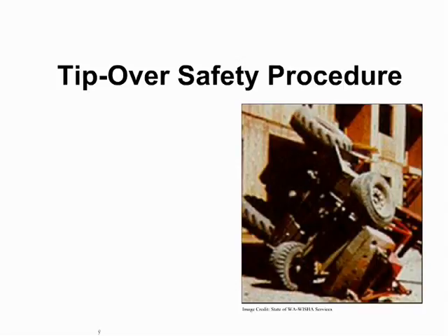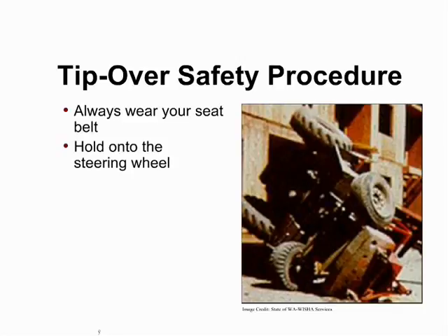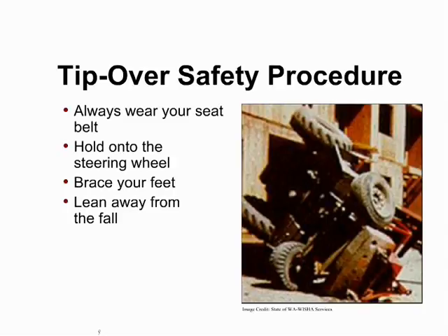Here are some important things to remember if you are ever in a forklift that tips over. Again, always wear your seatbelt. You could be killed by being thrown out. Do not try to jump clear of a tipping forklift. You could be crushed by the overhead guard or the mast. Hold firmly onto the steering wheel. Brace your feet and lean away from the direction of the fall.